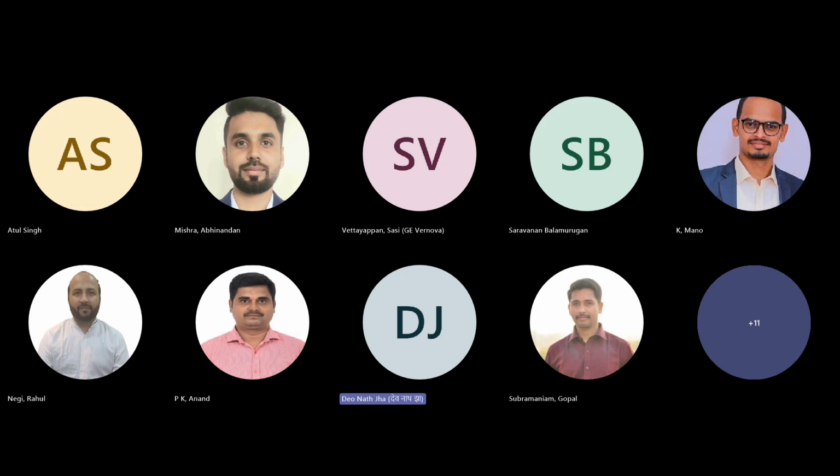Now, all these three models are equally important. We cannot say that I will not have a knowledge based or data driven model of the transformer because accuracy is lesser. A transformer digital twin is a combination of different models. If you want to apply a thermal model, it can be physics based, because there are established relations between temperature and moisture, which have been proven, and that model can be the most accurate.